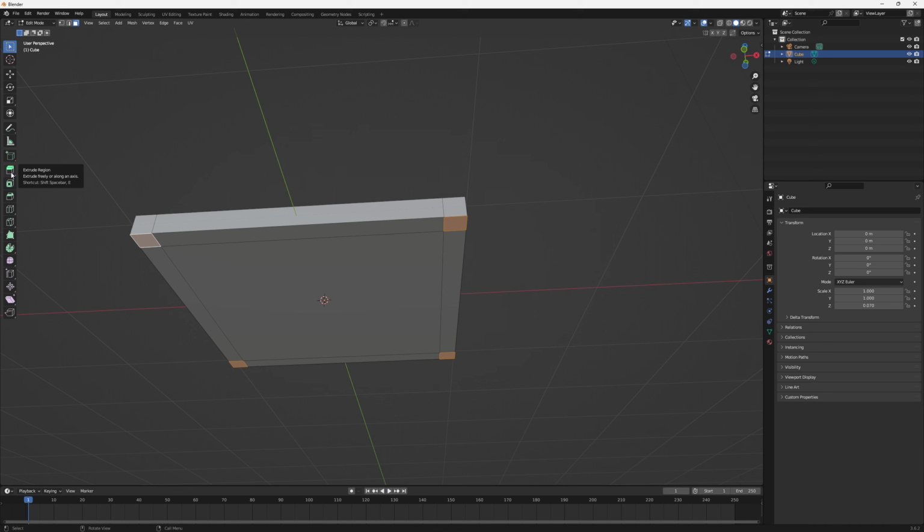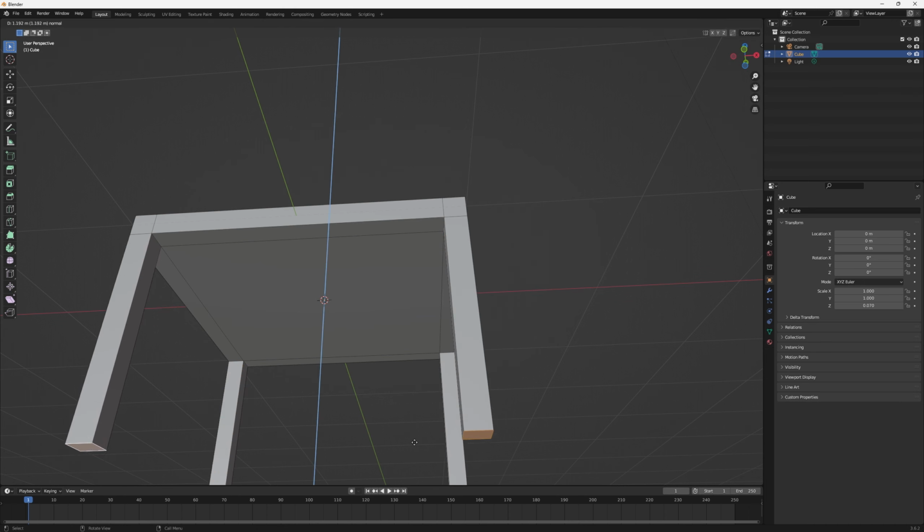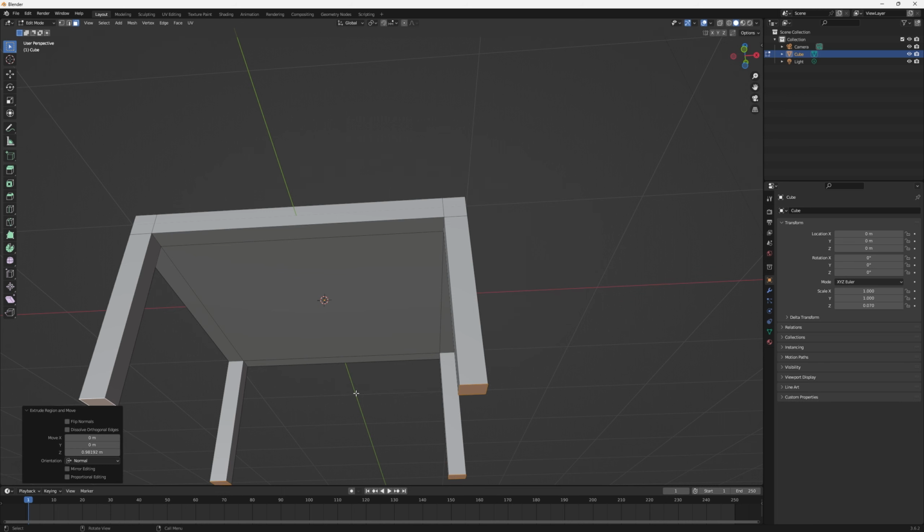So as I suggested before, the same goes here. Let's try always using shortcuts if you can remember them, rather than click on the tools here, okay? Because they might have slightly different orders of operation. So let's, without pressing it, just go back to the 3D scene and press E on the keyboard. Now, if you move your mouse up and down, you'll see that you're now extruding the legs out, and you can change their length. And once you're happy with their length, you can press the left mouse key to fix its length, like that.